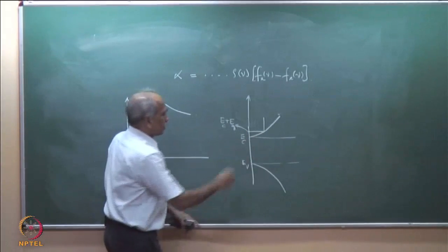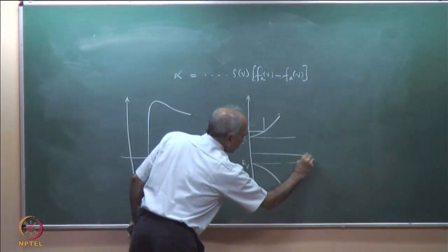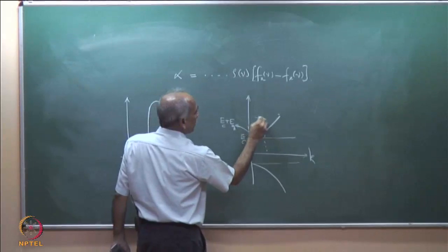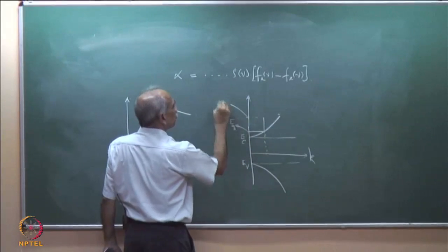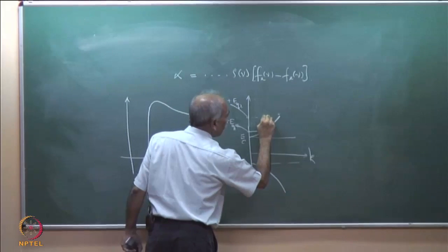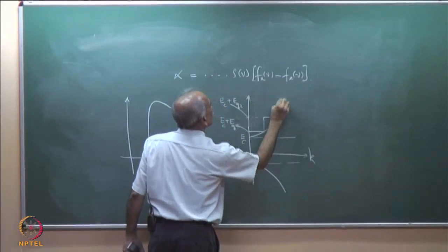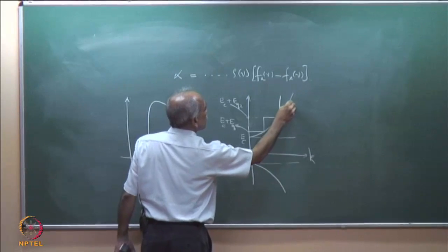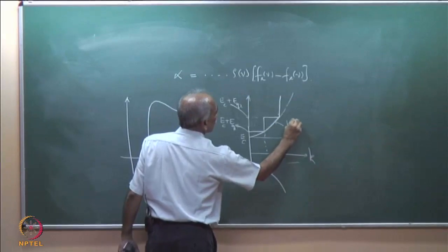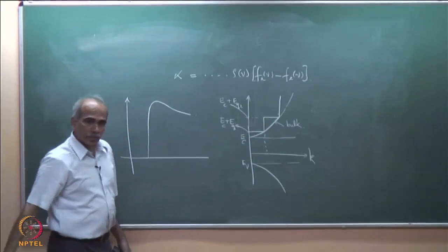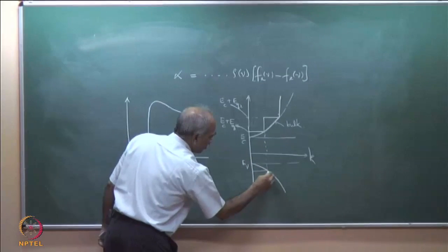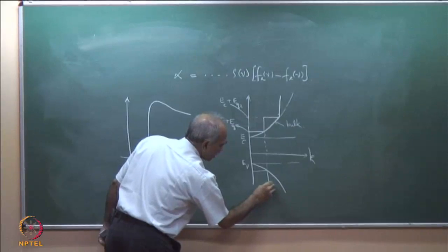The density of states was constant. Then when the energy reached Ec plus Eq2, there was a second step and then it continued like this. So, this is for the bulk and this is for the quantum well, and it is a step function. Same thing here, if I assume that mc equal to mv, then I will have a similar variation.